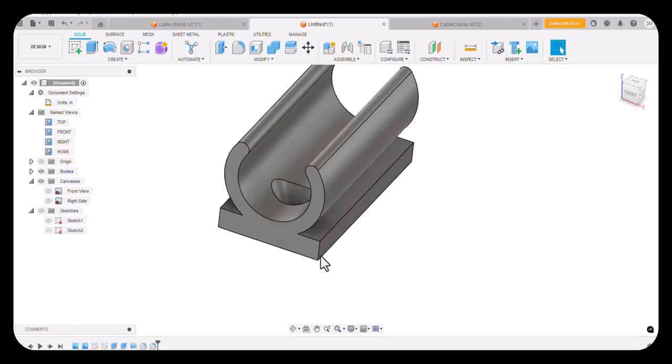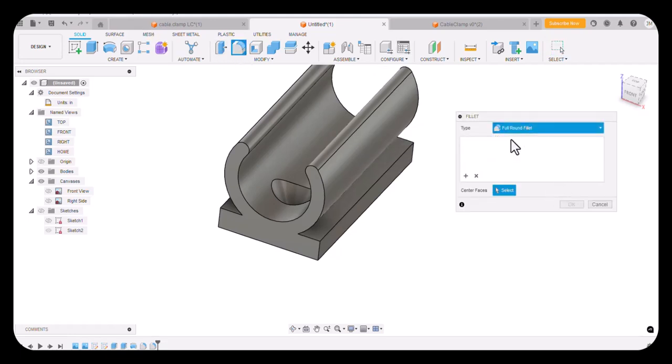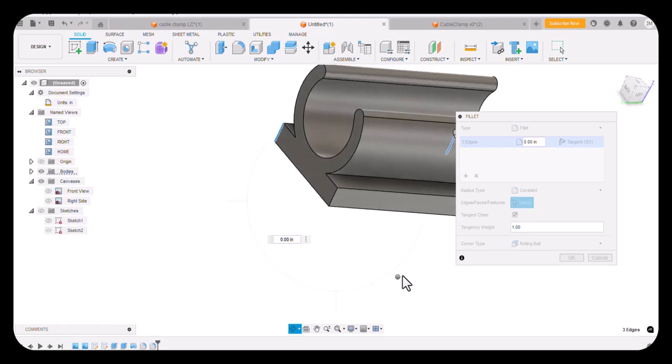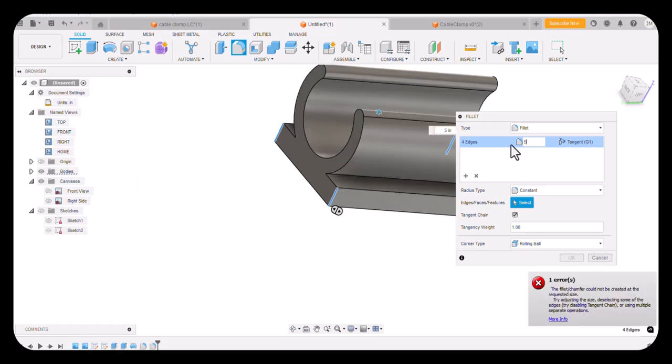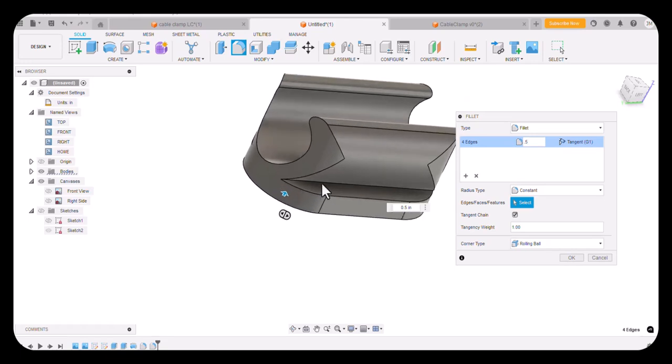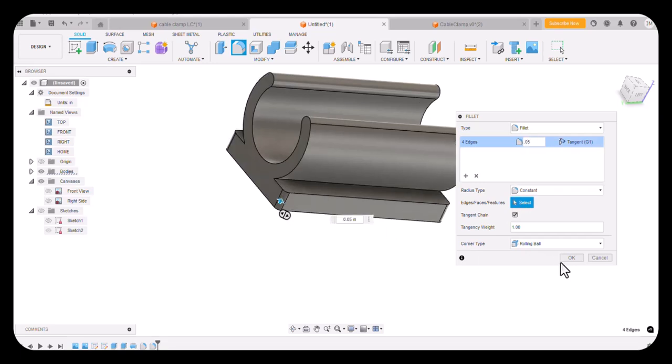And then I'm going to do these fillets as edge fillets. So I'll do fillet again, and I'm going to do just a fillet, which will give me an edge fillet. Now I prefer to put in these corners first, and so I'm going to go around, but the order in which you put your fillets depends on how you want this to look. And I'm going to do those as 0.05. Now I could go ahead and select the rest of these edges, but I want to do these first. I put in 5 instead of 0.5, and we'll see that. Now actually, when I did that, it went all the way around here. That's a ½ inch fillet. I meant 0.05, and so now we see those fillets in here.